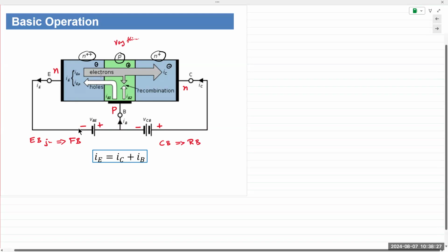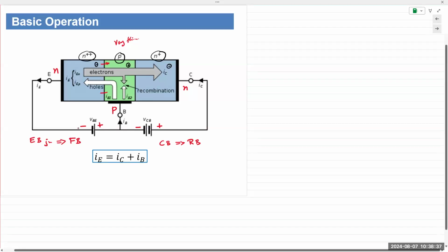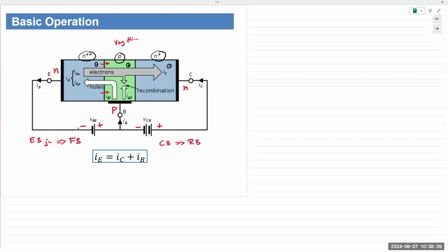Make sense? The PN junction, excess of charge carriers, excess of electrons in the emitter, and they cross over into the base region. The base region, two factors, physically very thin and electronically devoid of charge. Well, not devoid, but very few charge carriers available. And the charge carriers that are available are holes, positively charged holes. So some of the electrons from the emitter jump into those holes.